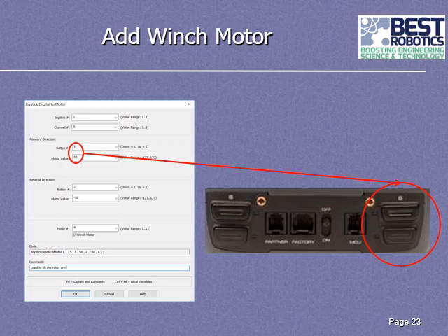So, as you can see, the button number 1 equates to, says down. If you look really closely, you'll see a U and a D on those 2 different buttons. There's an up button and a down button. The first button we're going to configure is number 1, which is the down button. And for this one, we're going to tell the motor to move at a rate of 50.